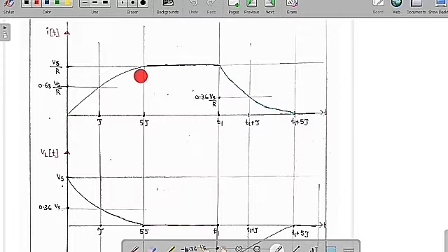At steady state, it is going to become charged. The current is going to become maximum, so here it will act like a short circuit. Initially open circuit and finally short circuit. So the final value is Vs by R and the initial value is 0. Within 5 tau, it is going to reach the maximum value. At t is equal to tau, it is going to become 63.2% of the maximum value. So this is the charging mode.